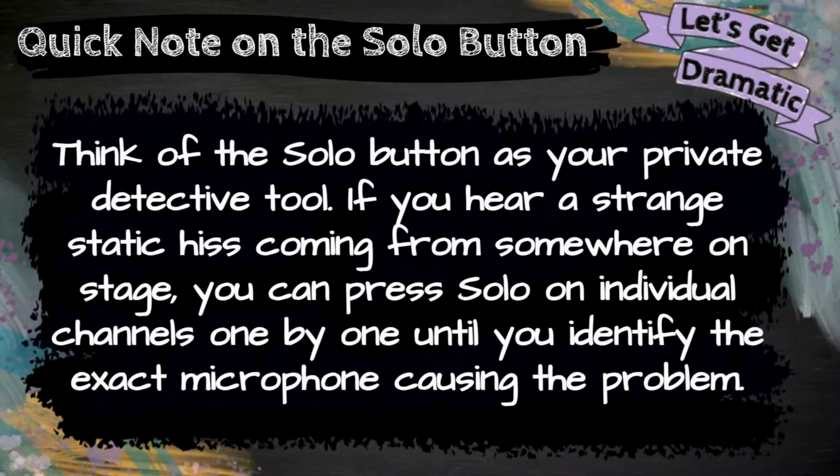Think of the solo button as your private detective tool. If you hear a strange static hiss coming from somewhere on stage, you can press solo on individual channels one by one until you identify the exact microphone causing the problem.